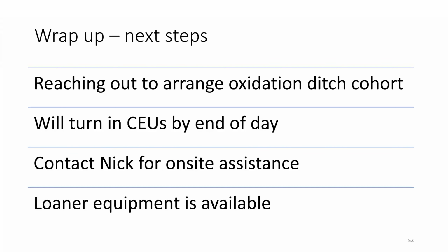But if you need to test influent ammonia, and you get high inflow ammonia, you'd want a range that goes up to maybe 50 or 60. I think the reason for that is just to eliminate friction that would keep operators from doing that process control testing. If there's one more step to it, it might not get done when things go haywire at the plant.